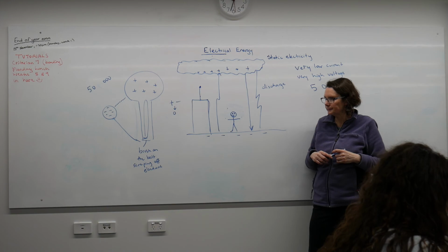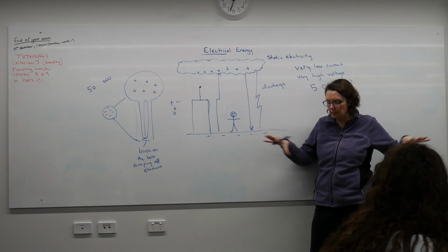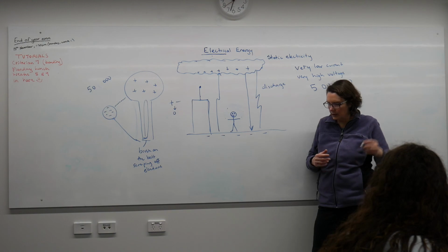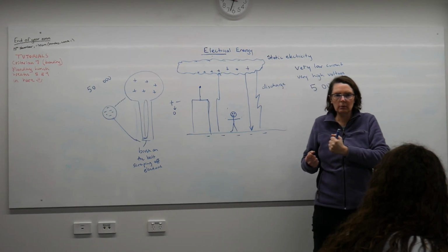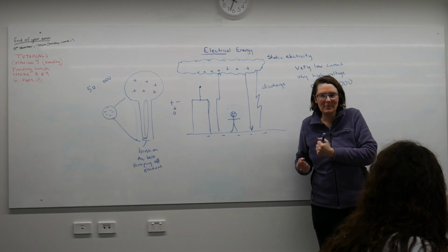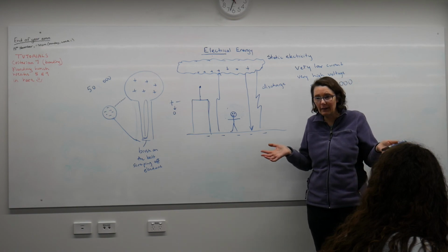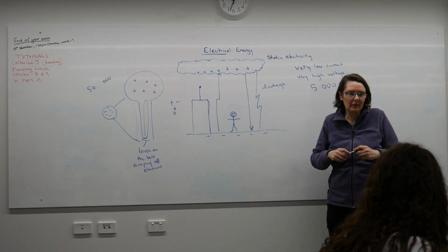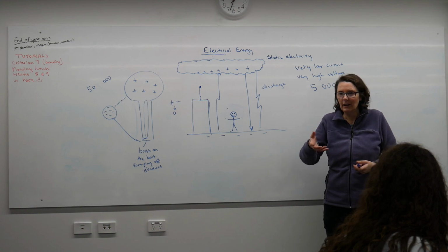How that happened was people in Queensland mainly were using a metal foil to insulate their roofs, and sometimes the installers were accidentally nailing that to the wiring, and then people's plumbing became electrified because the reflective layer in their roof was also sitting on top of the plumbing, and they would complain.